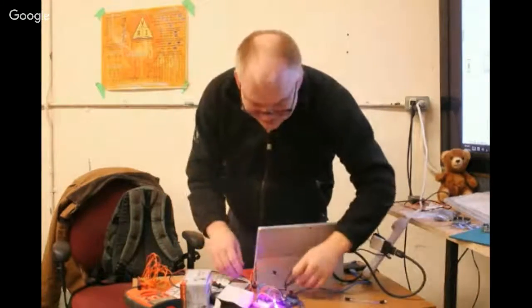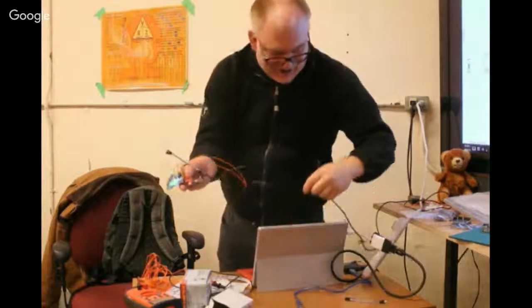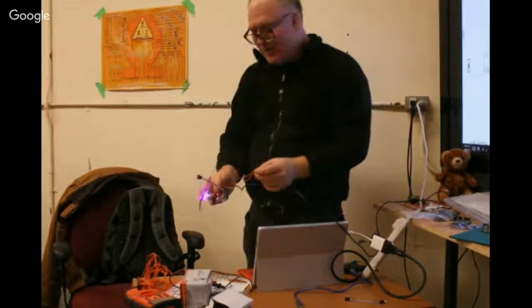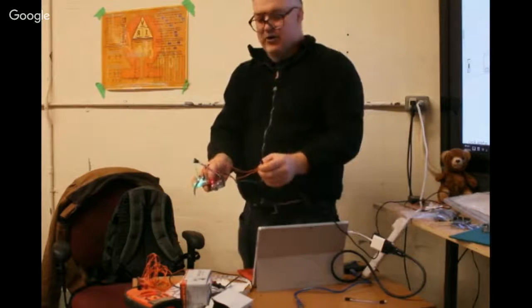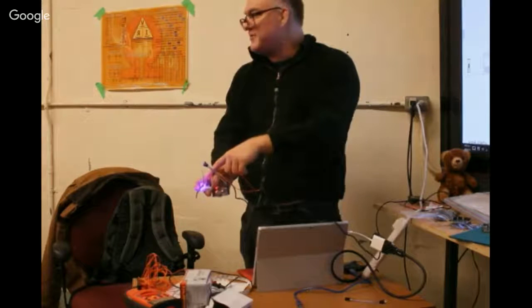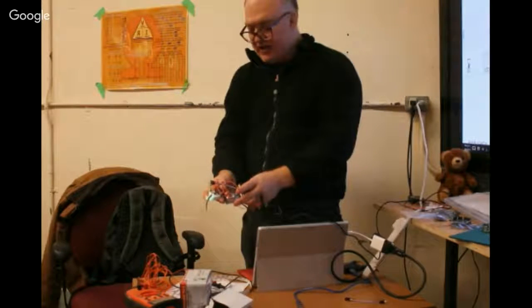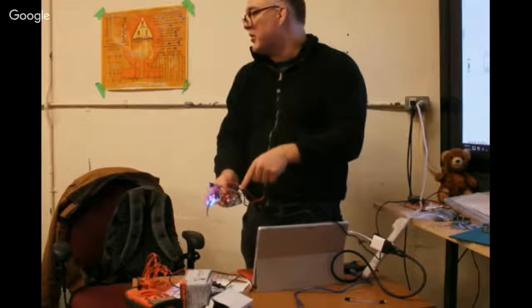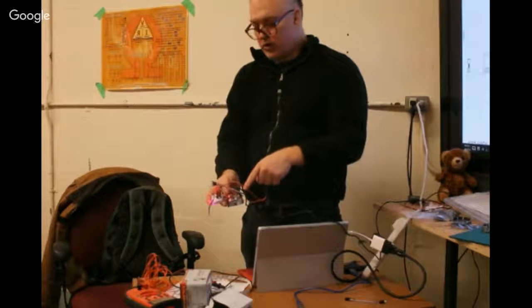So what I did with my power supply, and at some point you may end up doing something similar just to get the wires to be long enough to do what you want in your project, but there's no reason to right now, is I had cut the power supply wire and soldered 2 new wires to that so I could extend them directly to my expansion board. And the advantage this had for me is that then the positive current path never goes through the Arduino board. And so I wasn't at all worried about frying the Arduino board.